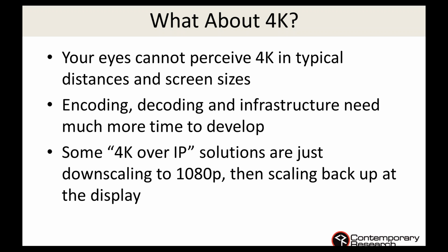Keep your eyes open. I was at CEDIA recently, so in a whole bunch of 4K signs and everything else. But what they were really doing is taking 4K, downscaling it down to 1080p, using standard MPEG streams to distribute the content, and then scaling it back up to 4K at the display. Not really the concept we're talking about. Most of the display manufacturers tell us, please just keep it 1080p. We know how to scale it for our TV. When I do scaling and downscaling and upscaling, then there's other artifacts and things we have to cope with, and it may not be optimal in the system.